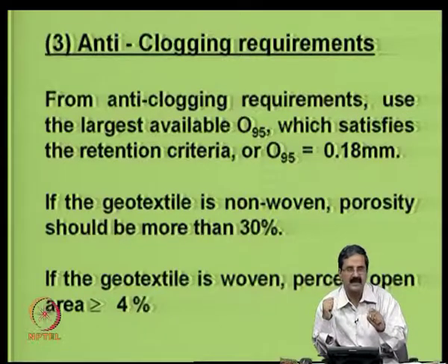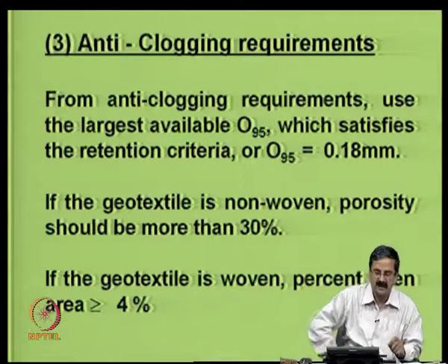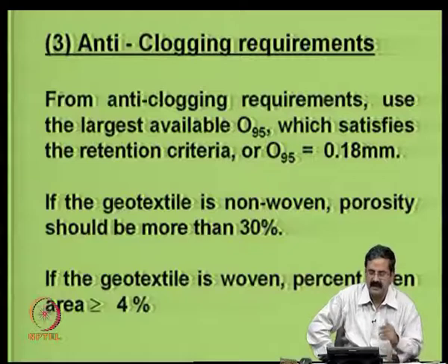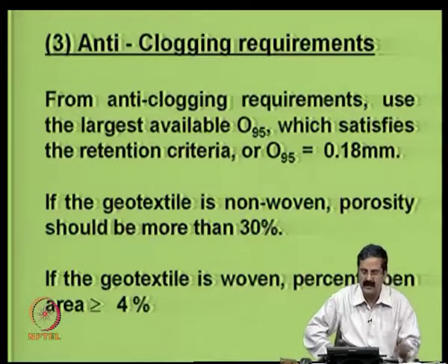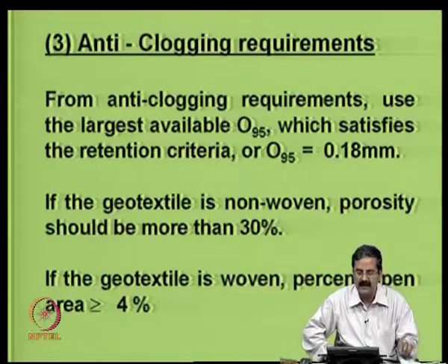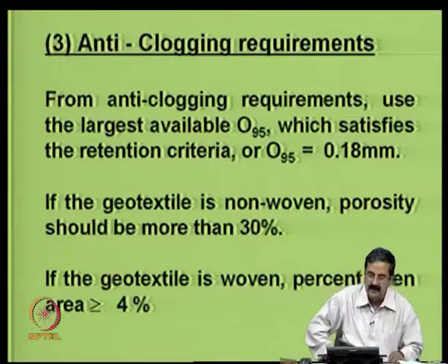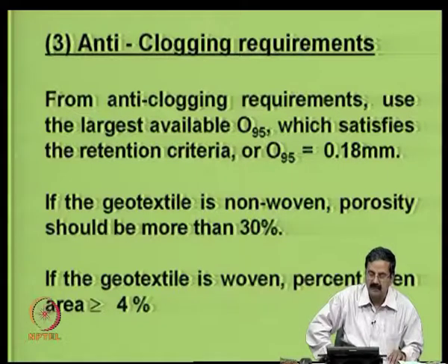We have to give a justification. If somebody asks you how did you take the retention and clogging criteria into consideration, I have to say, sir, I have taken 0.18 and I am trying to take a material that can be a little bigger than 0.18, like 0.2 I can take. So, some sort of decision one should make.